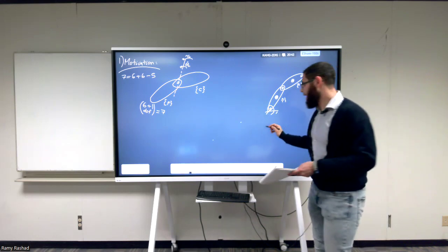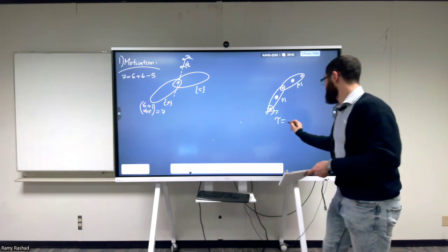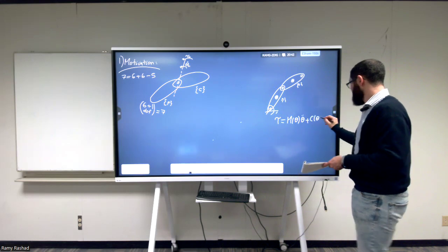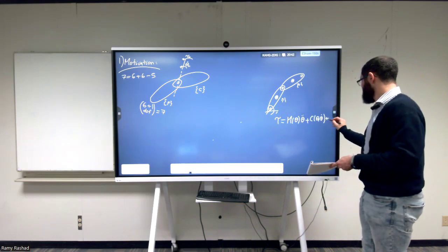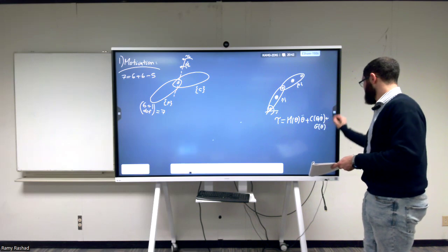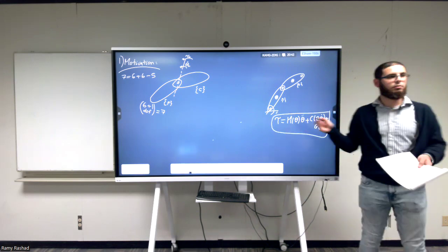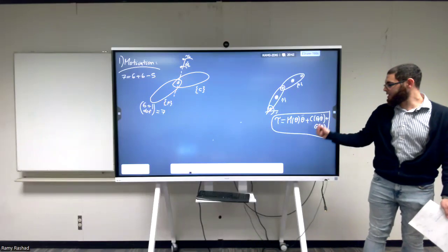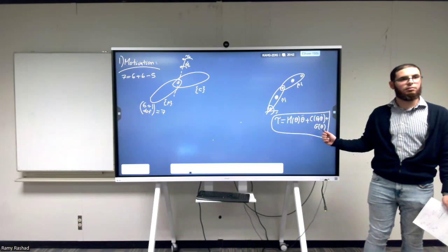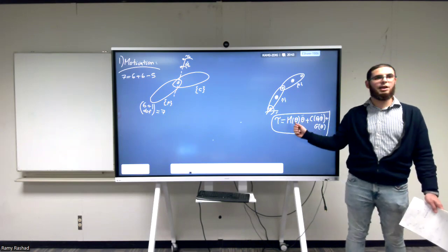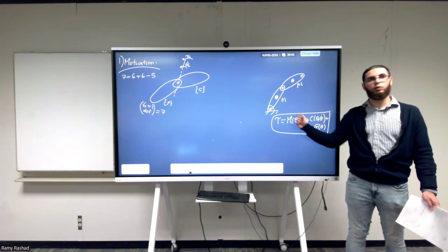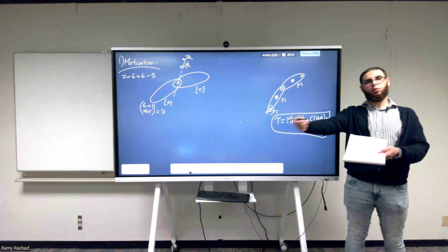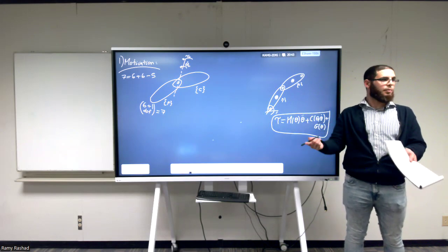In the end, we're going to have an equation that looks something like this. It's an M of theta multiplied by theta double dot, plus C of theta and theta dot, plus the gravity term, which is G of theta. If you took any course on robotics, this should be familiar to you. We just derived this for the pendulum. Of course, this term was 0. We didn't talk about gravity, so we were left only with this term, and the M here was constant. So this was the expression we derived today: the manipulator dynamics for the simplest manipulator in the world, which is just a one-link manipulator.